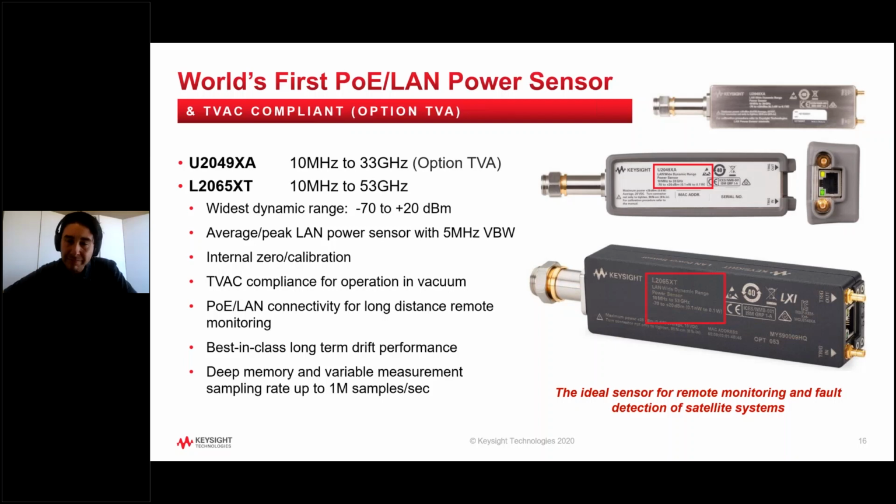For our LAN, there's a little bit more to do than just connecting a cable to it. These are power over Ethernet devices, which means that they obtain their DC power supply voltage from the Ethernet connection itself. So there is one piece of equipment that we must add. But from a trade-off of obtaining just excellent long distance remote monitoring, they are quite an incredible device.